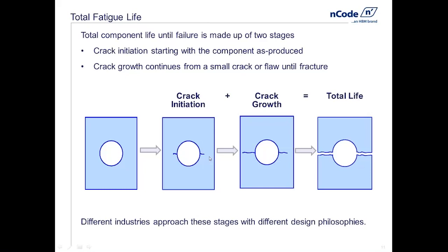For example, if we were designing crankshafts to go into an engine, very hard to get at, a very highly stressed environment, I would not want to allow a crack to start, because to have a crack initiated is to introduce a lot of risk, large warranty claim. If, on the other hand, I was designing an airplane, airplanes are full of cracks, they just happen to be growing at a low rate in a predictable fashion.